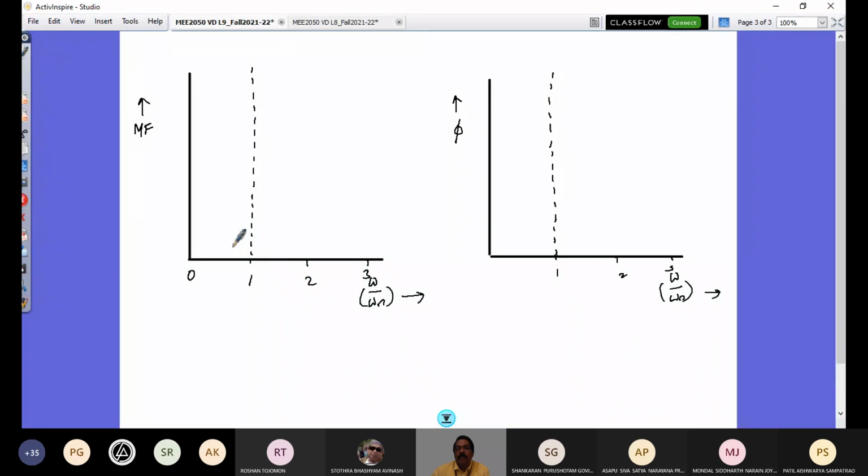Right? And similarly, on the y-axis, I'm going to have magnification factor values 1, 2, 3, and so on. This is an important one. When the magnification factor is 1, that means what? My dynamic amplitude during vibration is the same as what I felt at zero frequency excitation, or the degenerate system, as it is called. When I attach the mass with the spring and damper, the displacement that is there is called static deflection. If that is the same for a dynamic condition as well, when this forcing function is there, then that is called the magnification factor 1.